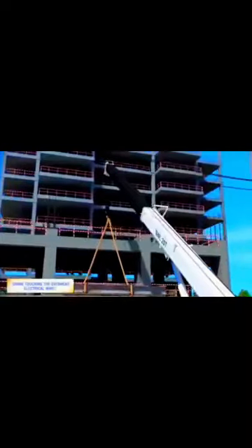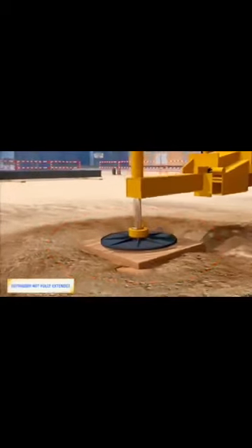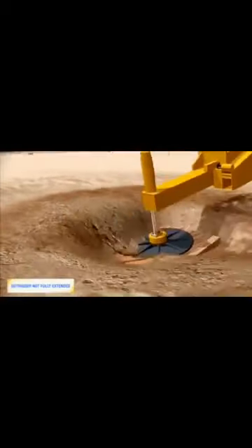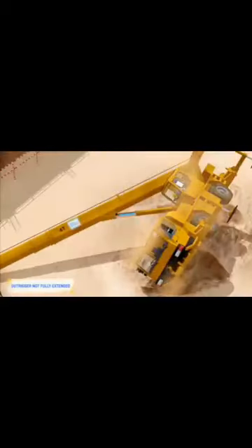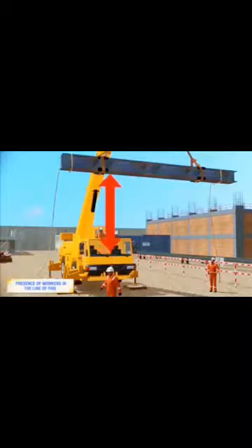Any part of the crane touching the overhead electrical wires, which can result in electrocution. Grounds not being firm and outrigger not fully extended, which may result in tripping, imbalance or trapping of the crane. Presence of workers in the line of fire.